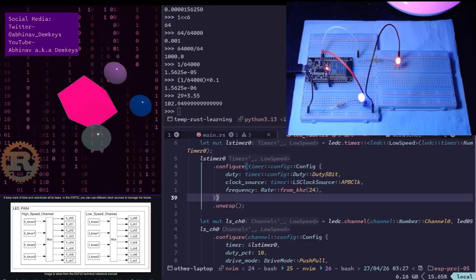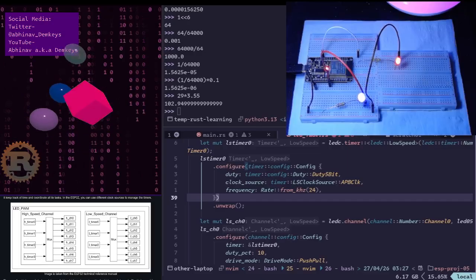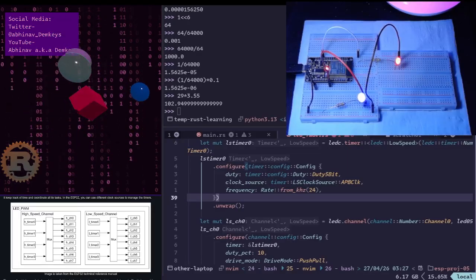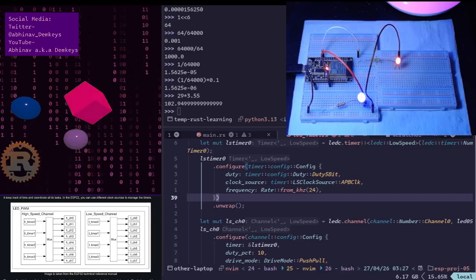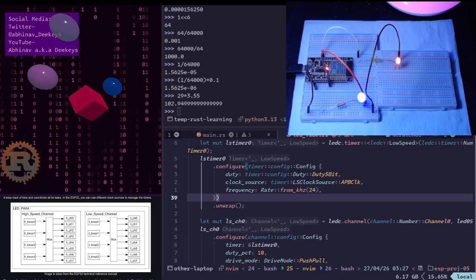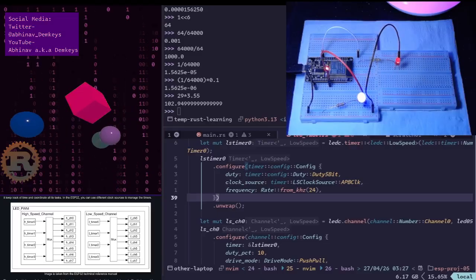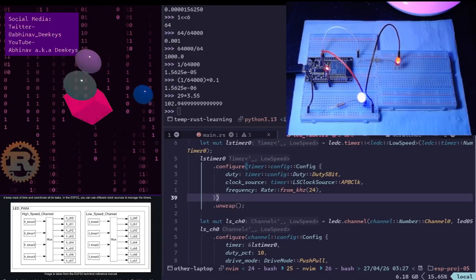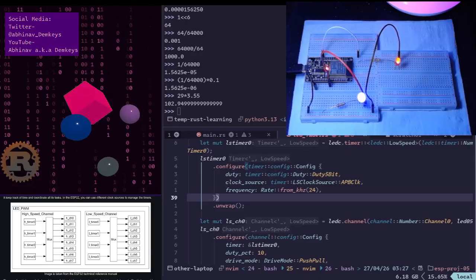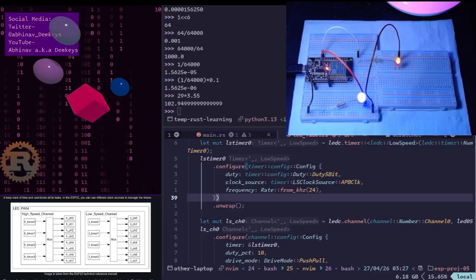But now I know about it. Before knowing this, I didn't realize that in the ESP32, you can actually turn off certain portions of the hardware. So, for example, you have the PWM hardware, and then you also have the CPU hardware. These are separate pieces of hardware.